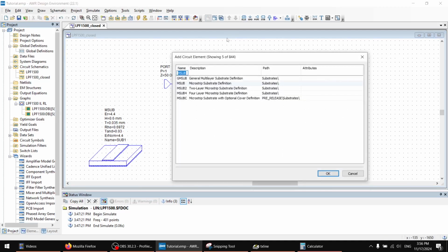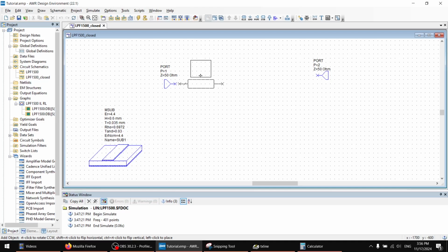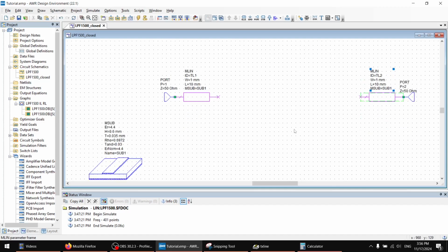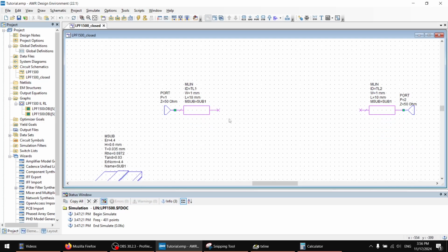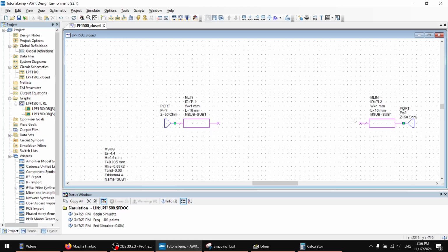Next, since we are aiming for something physical, let's add 50 ohm traces that will be put close to these ports, which you can also treat as connectors, right? So I will copy and paste this here. Length is okay, but the width, here you can set the width, and we're not going to set everything manually, because if we want to change this in the future, then we'll run into some troubles, of course, by changing everything in our schematic.